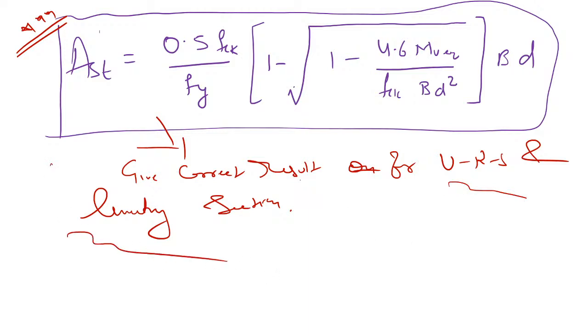But my dear friend, remember one more thing. Most of the torsional problems when it comes to design, whose sizes are fixed, are like your under or limiting case. They will not generally go over reinforced section. So the majority of the times this formula will be satisfied.